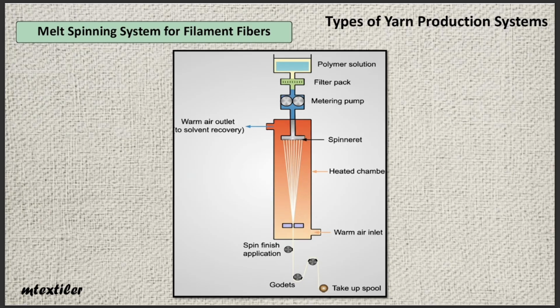The solid filaments are drawn between the rollers, and after drawing, there can also be a controlled heating stage to stabilize all the fiber and yarn properties. After that, by means of winding rollers, the continuous filament fibers produced are wound onto a bobbin. At the end of this stage, or in subsequent stages, we can transform the yarn from smooth to textured, similar to natural fibers and wavy, through various texturing processes. Also, after production, we can cut them through cutting machines to obtain fibers of different lengths.